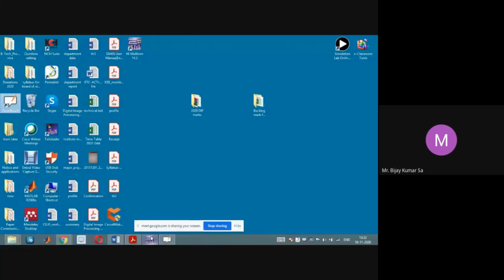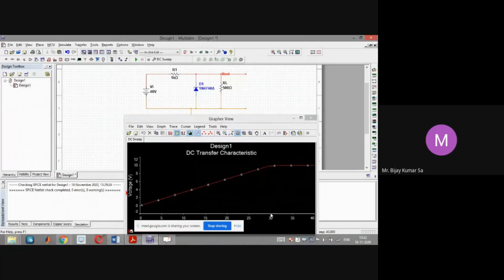Here also in this graph you see that beyond Vi minimum, V output becomes equal to this value, which is almost Vz, close to 10.05, and we have already measured in the multimeter, it is 9.98 volt, it is almost equal to Vz. So the entire thing is quite getting reflected in this plot.